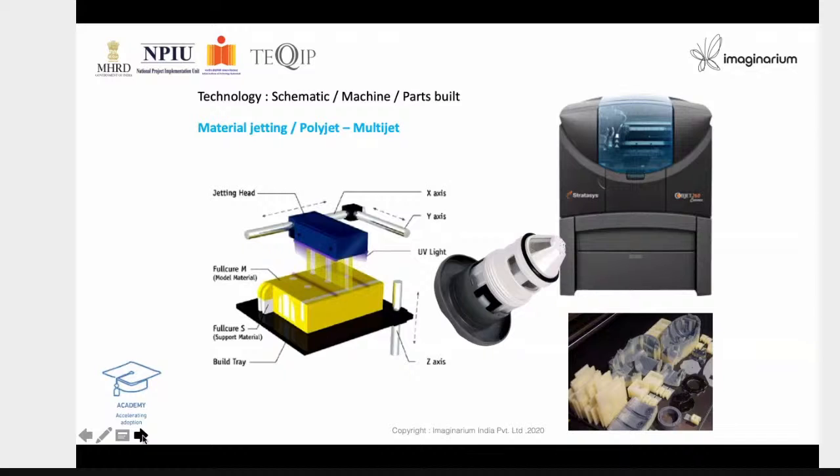You can see a floating manifold, what you see here, as though it is in zero gravity. That actually shows a neoprene rubber-like o-ring, which is very soft. The manifold, which is in light gray, is very strong like ABS. And the bottom actuator is also like ABS inside, but to touch it is soft. That means it has got a cover of soft material. All such things are possible with PolyJet, multi-jet, material jetting technology. It's wonderful. In fact, we can make a lot of things, medical models and all that, done very easily using this technology.